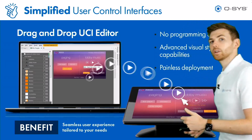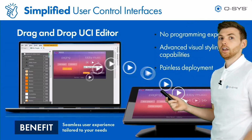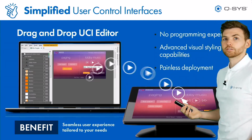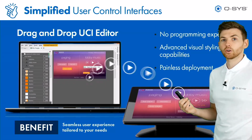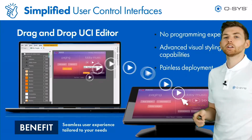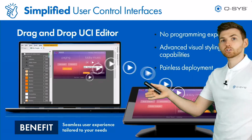And you can see here that we can build UCIs really, really easily. Inside the Q-SYS Designer software, you can just drag and drop controls from the schematic onto the user interface and build UCIs that look however you need them to look. You can style them by adding custom graphics and changing the colors, and it's really easy to do.